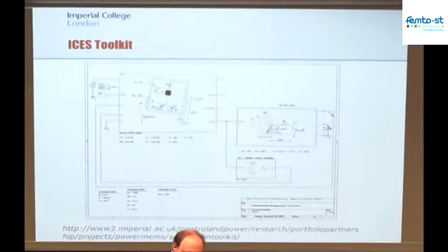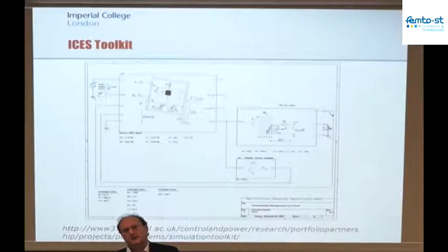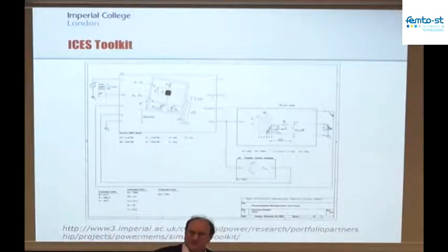So we did some work recently in collaboration with UC Berkeley, looking at the complete optimization of a piezoelectric system. And that was trying to optimize everything from the shape of the cantilever, how big a mass you put, how much flexing of the cantilever you could have, all of these things, plus the optimization of the electric circuit. And the optimization of the circuit then included things down to the detail of the doping profile in the MOSFETs that we used as the switches. So we did this massive optimization on all of these things. And we got a bunch of results, and I'll share the paper with you.